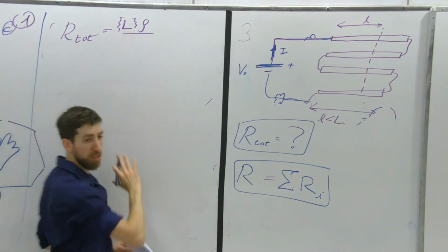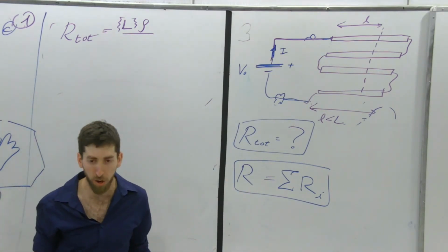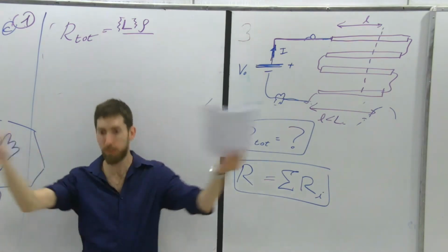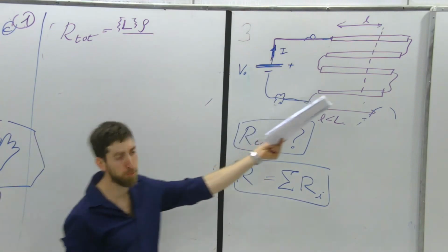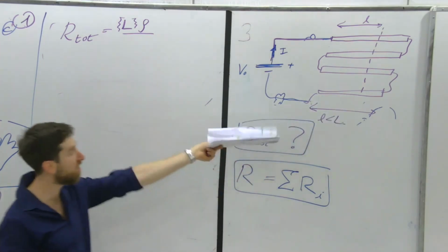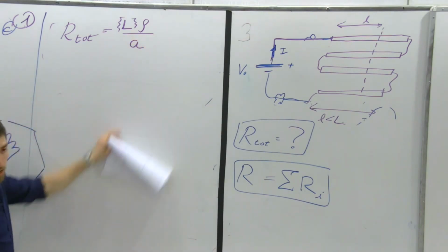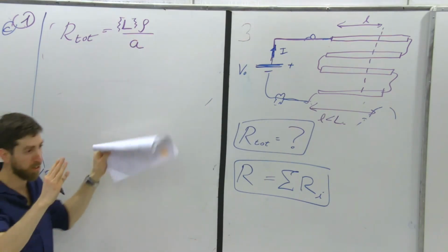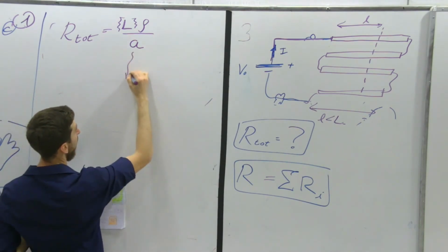If the length changed, the material should have come from somewhere, right? There's no material that shows up suddenly. We didn't do some chemistry experiment. We just smashed this thing, right? Just went with the car over the iPhone. So actually we have here some new area. Let's call it small a. Why? Because if it was stretched, then it becomes smaller in area. So we actually need to find this.